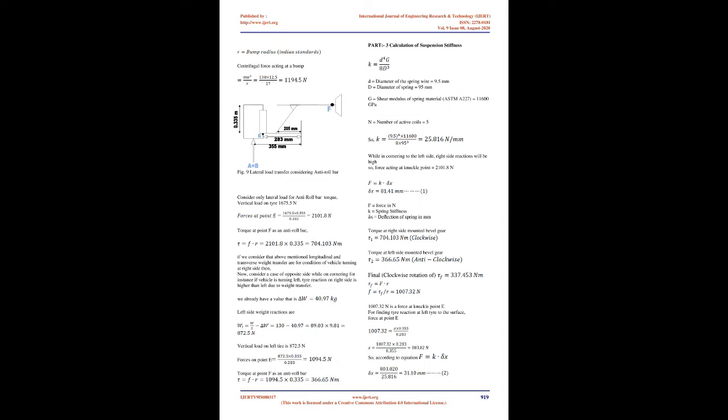The shape of anti-roll bars for automobile suspension systems is usually designed from the standpoint of avoiding physical interference with other components mounted on the bottom of a vehicle. Also, the diameter of the bar is usually pre-selected and fixed to achieve a desired anti-roll stiffness. After having this many constraints in shape and dimensions, there is little design flexibility for engineers and designers.